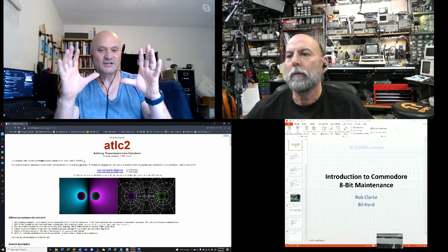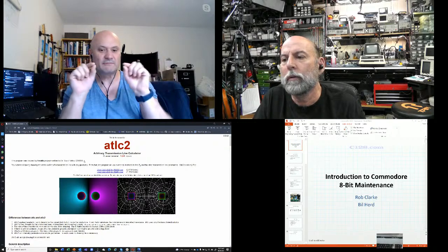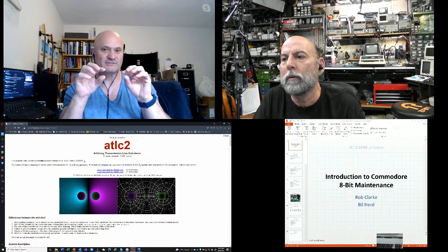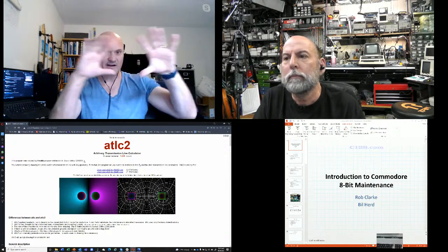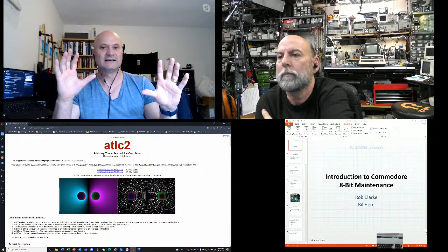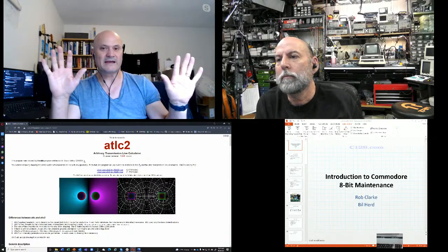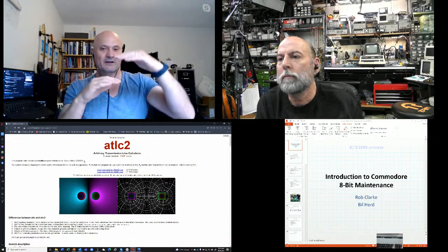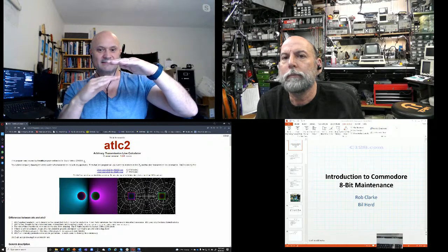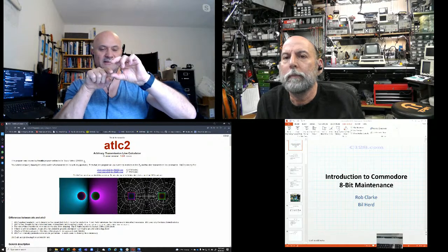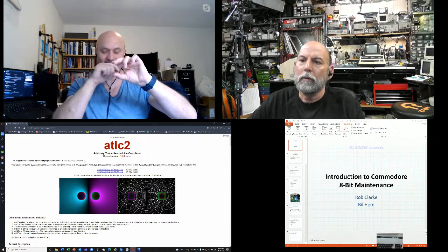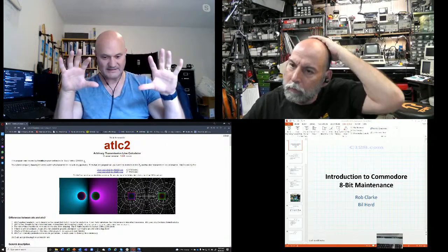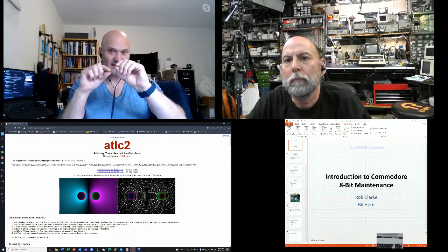it takes a generic bitmap where different colors in your bitmap represent different materials in the cross section, and then it divides the whole thing up pixel by pixel. It gives you a pixel by pixel mesh, and it calculates, okay, between this conductor and this, we have all these little pixels that represent FR4 in a PCB, and all these ones that represent air. And it creates that mesh of theoretical